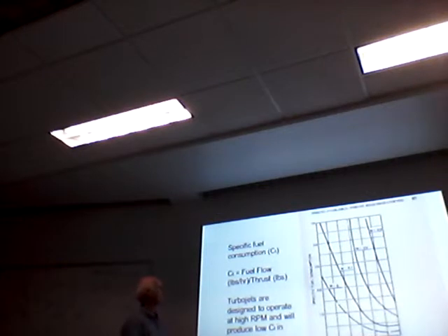Okay. We would like to have specific fuel consumption. Low numbers would be good. And where those low numbers occur for turbojet aircraft, one of them is counterintuitive. High RPM is the most efficient fuel use. Doesn't mean it burns less fuel, but it's the most efficient. And again, M is military flight. Yeah, no afterburner. Okay, and don't worry about that.